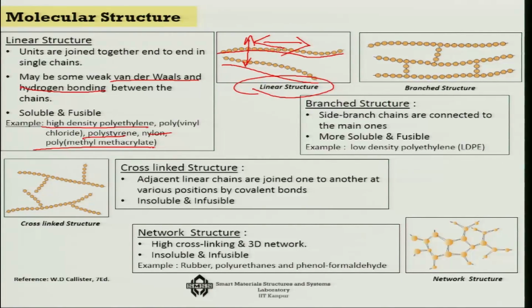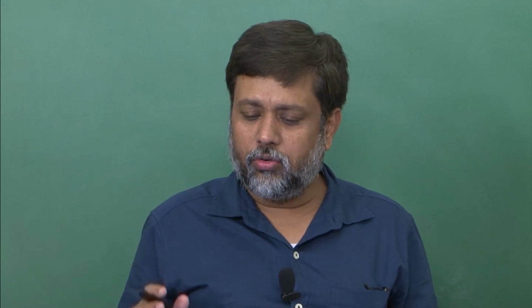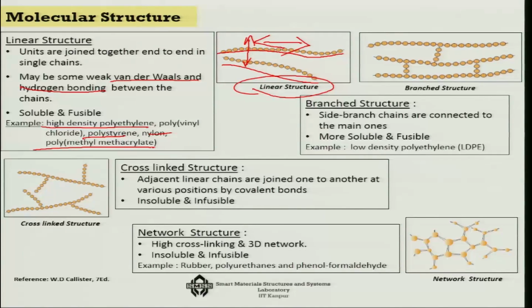The other point is that linear structures generally have a good crystal structure. Because their repeatability is generally very good, many of the linear structures, not all but many of them, are highly crystalline. So if the degree of crystallinity increases, that also improves the mechanical property of the system. Now some of the linear structures are not just linear, but branched types of structures.